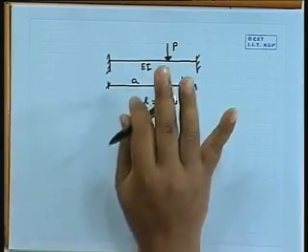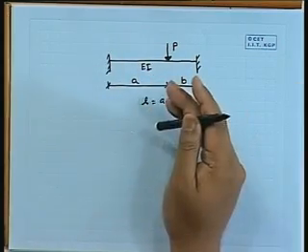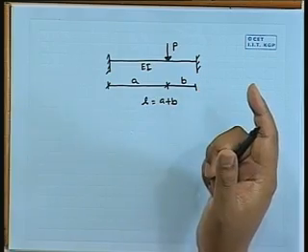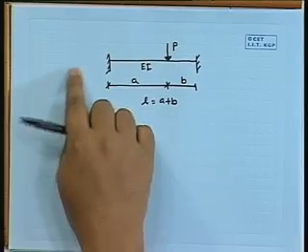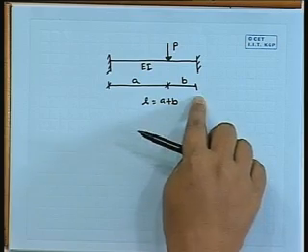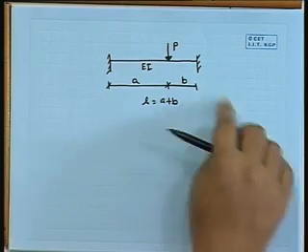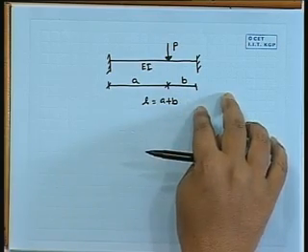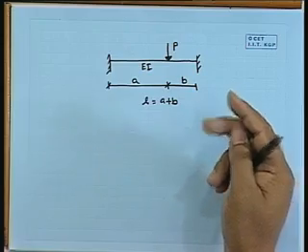So basically we have two equations apart from the horizontal equation. We can take one vertical reaction, one moment. So one vertical, another rotation, that part will be extra. So two additional unknowns are there. So your degree of indeterminacy is equal to 2, right.